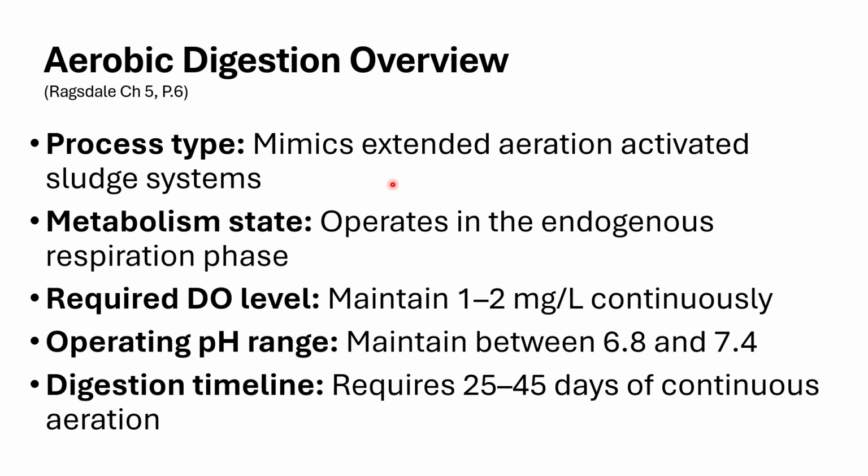We're allowing those bacteria to do their job and concentrate solids at the bottom of the digester by freeing up that water that's going to stay at the top of the column. It operates in what's called the endogenous respiration phase, which means it's taking in oxygen, processing the organics, and expiring carbon dioxide. That's a fancy way of saying this type of respiration, okay?